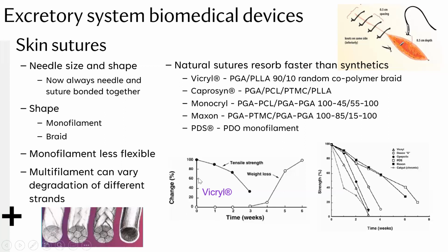And this is showing also, in terms of time, the change of tensile strength, but also the weight. So as you can see, they're gradually degrading, meaning that you're actually losing weight, but it doesn't happen until degradation hits a point where these materials are consumed. It's usually the coating around these that protects them for a while until it starts losing weight and being absorbed into the matrix.